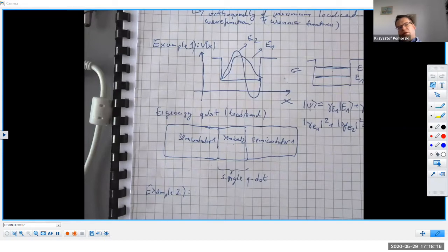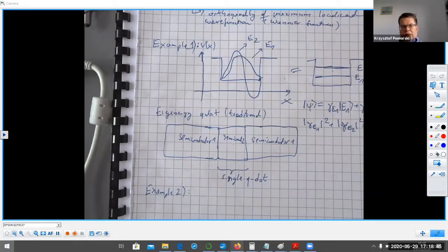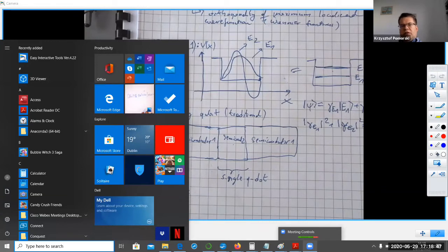It is also a very remarkable feature of CMOS technology that if you have a very small channel length in a CMOS transistor, what happens is that instead of thermal activation of electric charge, as we have in classical semiconductor electronics, you have the activation by the gradient of the electric field generated by the gates.